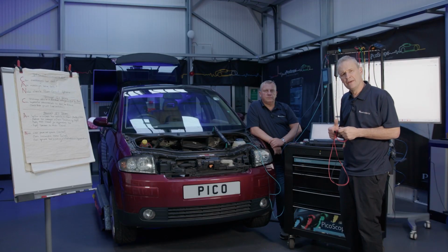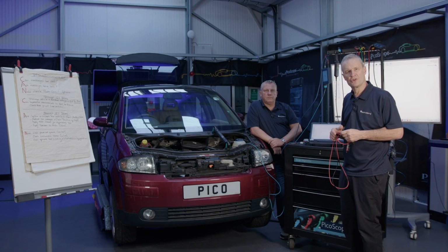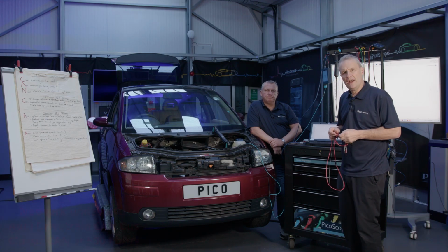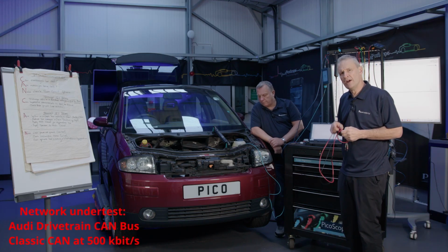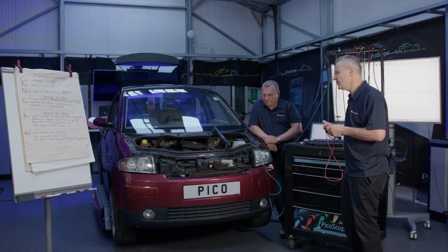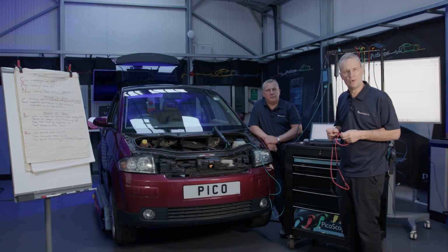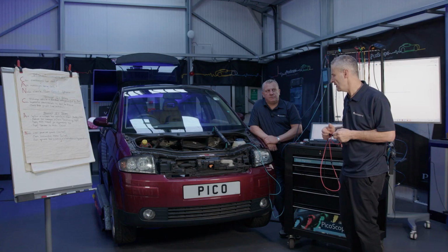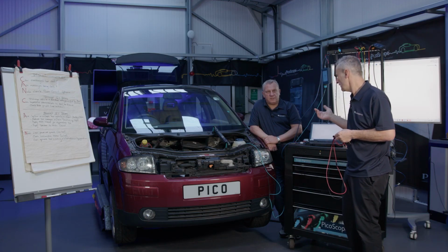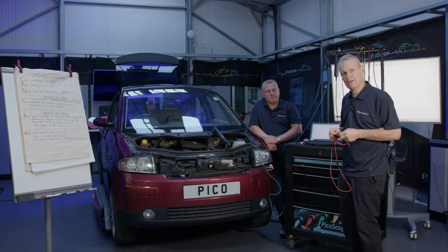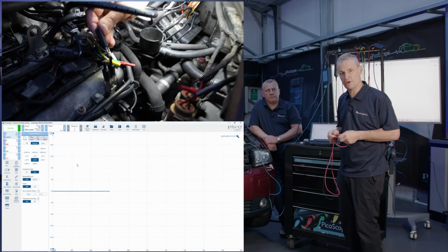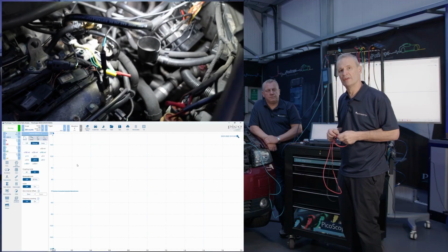Okay, so can messages be sent? The first one was, of course, we've made sure this vehicle is at 0 volts and fully discharged. We wanted to check before we go down the impedance route, actually for voltage on the CAN bus, which you ask yourself, well, the vehicle's dead, so why are we doing that? In my experience, I've had a couple of issues, and I think you mentioned, was it tracker? Trackers, yeah. Anything self-powered on the vehicle that may be connected to CAN has a potential to leave voltage on the CAN, especially when we've got the vehicle disconnected.